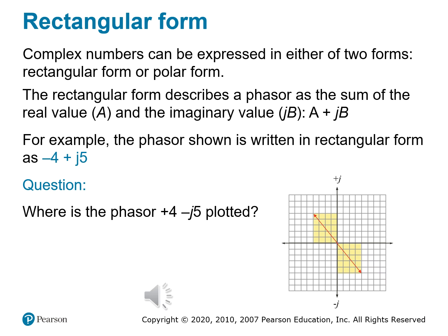So when you analyze RC or RL circuits, we often shift between rectangular and polar forms. I mentioned why we do that before. Sometimes it's just easier to do mathematics in polar form and other mathematics in rectangular form. And we'll get into the details of that later. Rectangular is actually excellent for addition and subtraction, especially in series or parallel combinations, just like how you add inductive reactance and resistance on perpendicular axes. You'll do the same here. The rectangular form helps us see the structure of complex impedances or voltages before converting to polar for magnitude and phase angle.